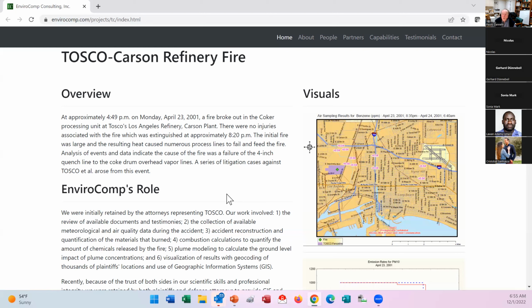So if you use the standard Gaussian model, Gaussian plume or Gaussian puff, you have to be very careful, because the Gaussian model will open the plume and the plume touches the ground. Sometimes with fire, that doesn't happen, or it is only a small fraction of the plume that touches the ground. Most of the plume remains there, aloft, and you can see it.